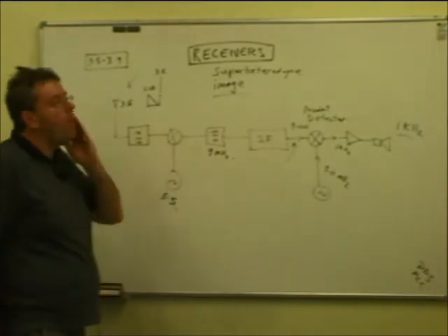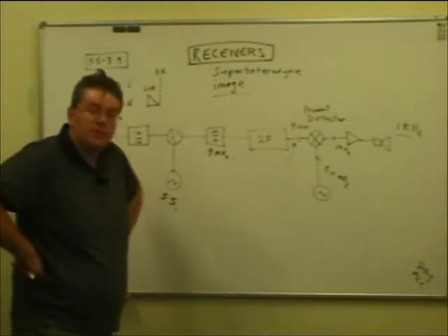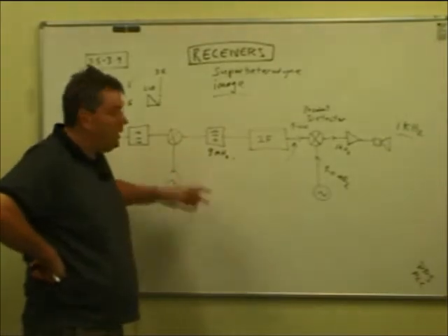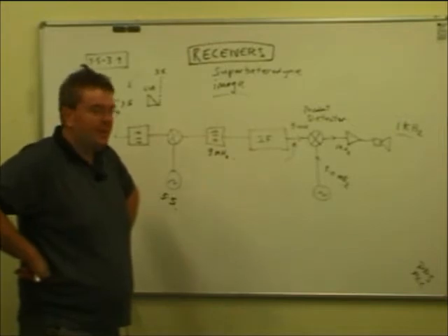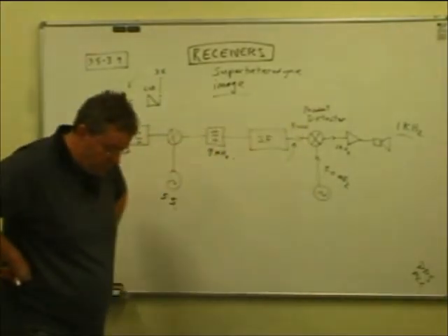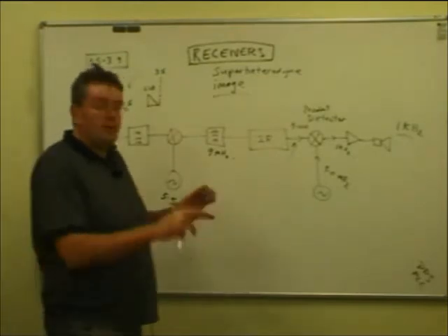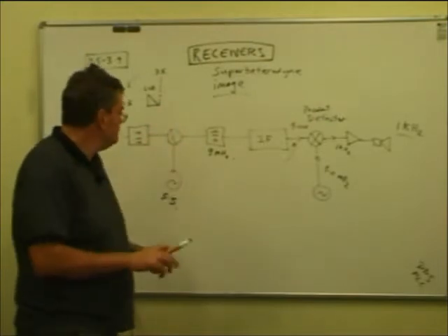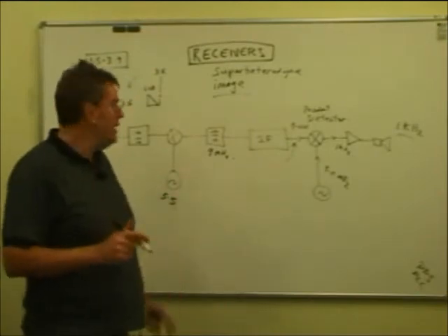Right. The requirements for the filter in radios that receive different modes, as in single sideband or Morse or AM or so on, are different. If we want to receive AM, we have to be able to fit the upper and the lower sideband signal through. So if the highest speech frequency that's been put onto the AM carrier is, say, 2.5 kilohertz for communications quality, then the filter is going to have to be 5 kilohertz wide. Remember that the AM signal is twice as wide as the highest modulating signal. If we want to receive single sideband, typically it's about half that, around 2.1, 2.4, 2.8 kilohertz.